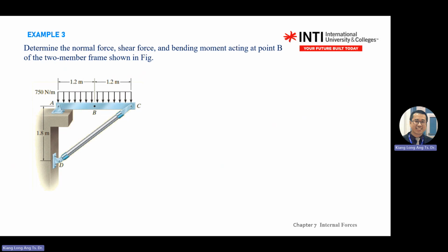Okay. Then after that, you solve external reaction force. The focus is asked you on this member. So when you focus on this member, convert this reaction, this connector here into forces. This one you assume the force will be, if this one press down, what does C point feel? You will feel the force pressing in or pulling out. Press, right? If your C point, you'll see this one poking inside. So the force will be like this for C lah.